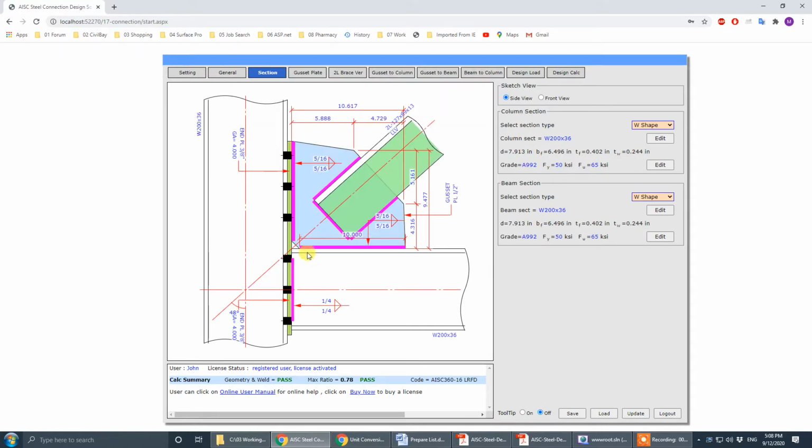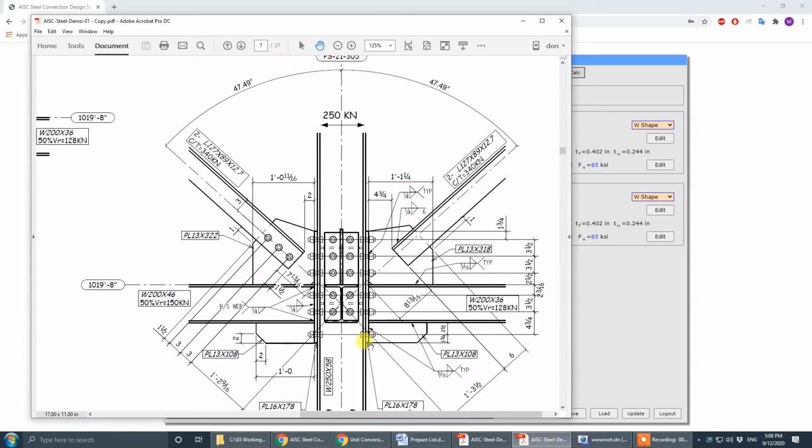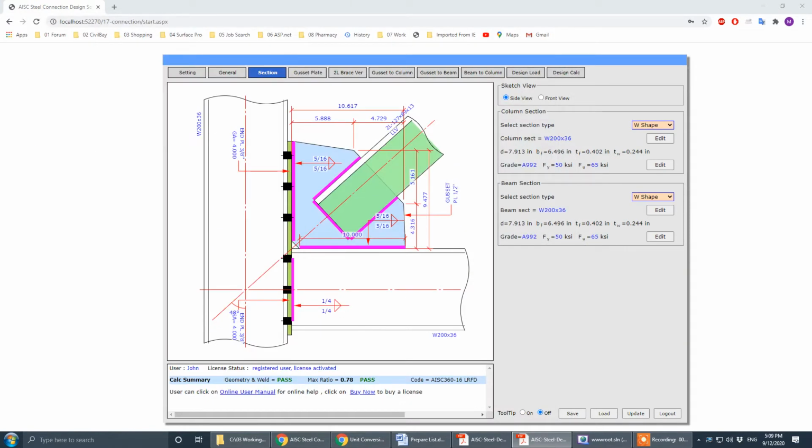236, 2 rows. Now is 2 rows extend 1. Okay, 2 rows extend 1 with a stiffener plate here, so I can only extend both. All right, so I will consider, the program will consider this row and this row belongs to beam to column. Okay, so I'll go to see here, I will add rows here, beam to column.